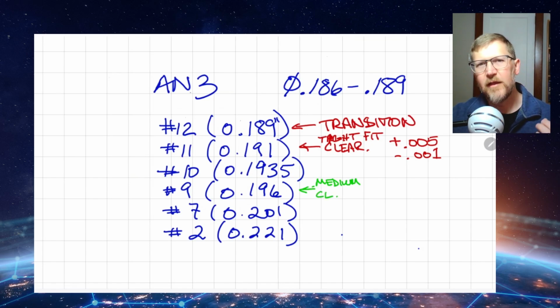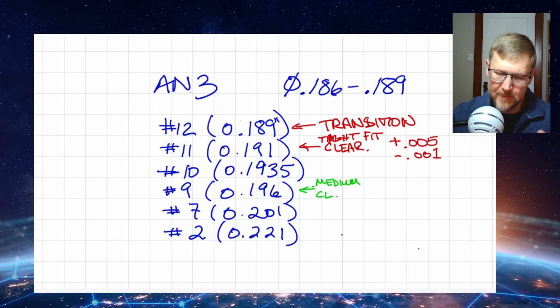That clearance can be useful if you want a reasonably tight fit, but not so tight that it makes it very difficult to manufacture. We'll come back to positional tolerances and that sort of thing, but this has some good utility in machined components. And so that's where you're going to see that used quite often.